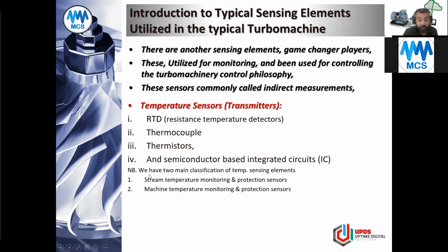Once it is in touch with the media, like a gas compressor where you would like to know the performance and control the temperature, you need to put a temperature transmitter somewhere on the pipe itself, the discharge or the suction, according to the designer, to know exactly what the stream monitoring is. This is indirectly connected to your vibration monitoring system, where it can control the machine, because it connects to the DCS, which at the end is the major brain of your system.